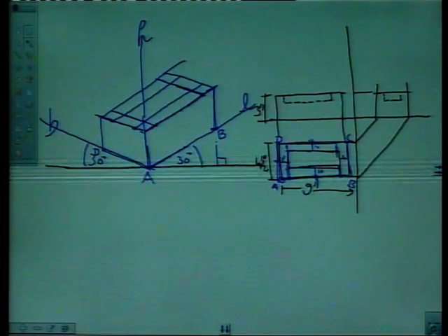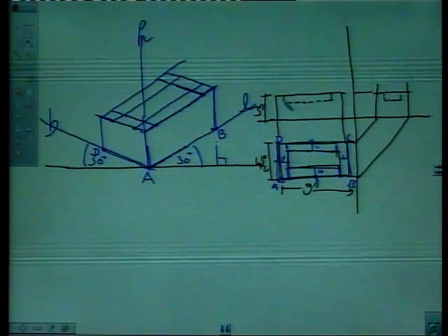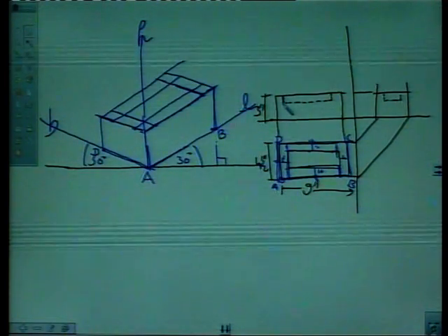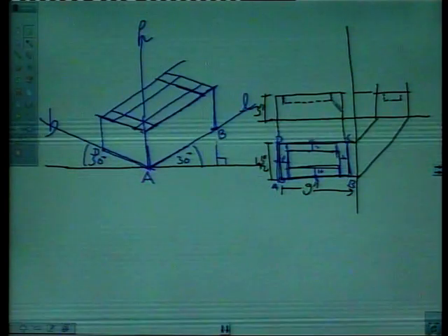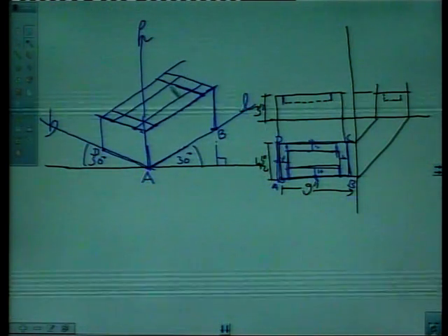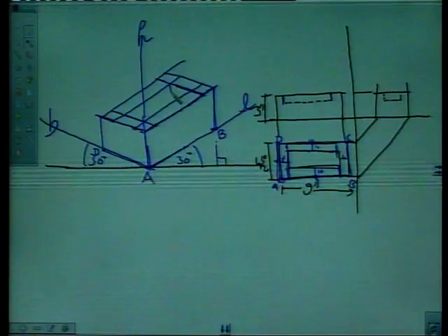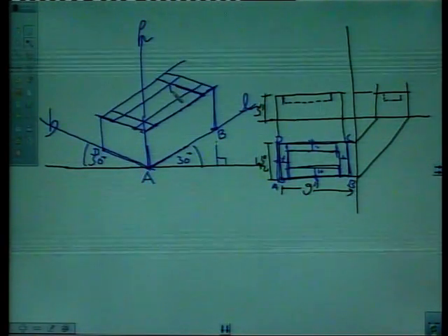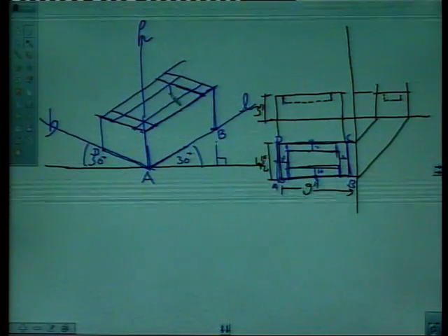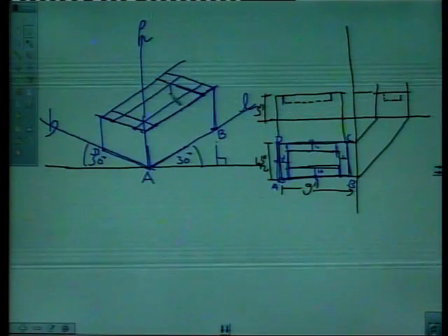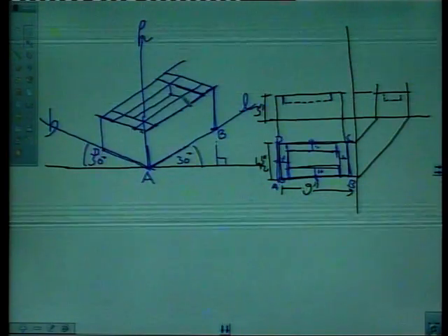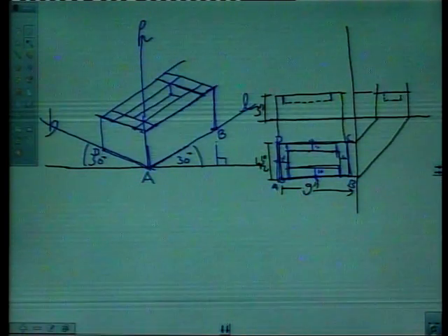And how to mark the depth of the frog? Say the depth is half inch. As per the statement from isometrics, vertical lines remain vertical. So depth will be visible only from this corner like this. Draw a vertical line downward. This line is also perpendicular to the ground, and mark say half inch here and draw a parallel line like this, right? This represents the depth of the frog.